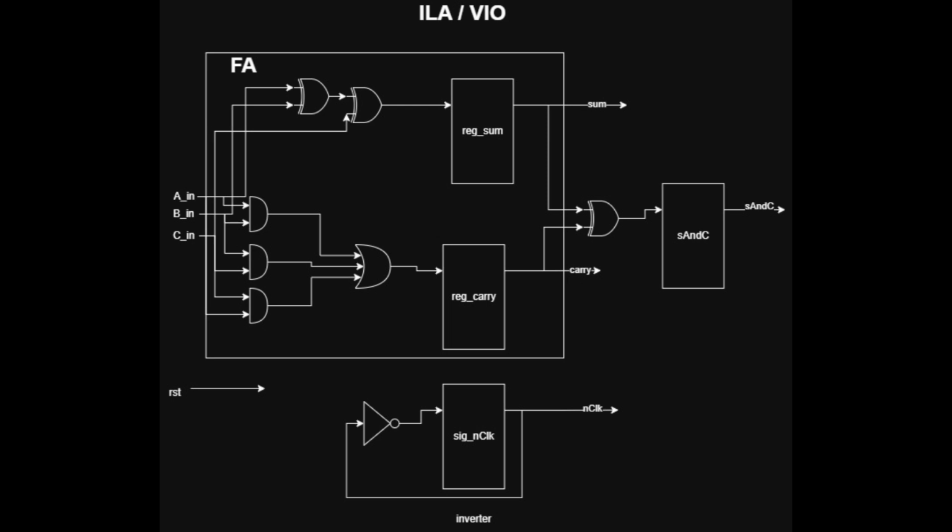Today we'll be talking about the virtual input output and the integrated logic analyzer, and we're going to do that by implementing this modified full adder in Vivado using VHDL. We're going to use the ILA to be able to observe our inputs and outputs, and we are going to use the virtual input output to be able to drive our inputs and retrieve our